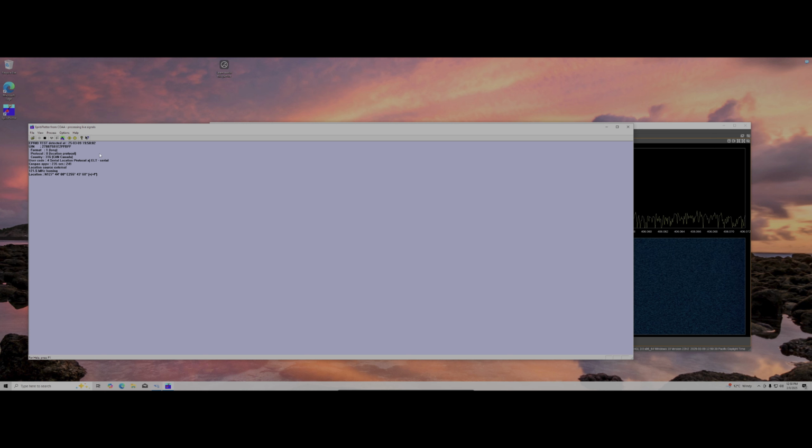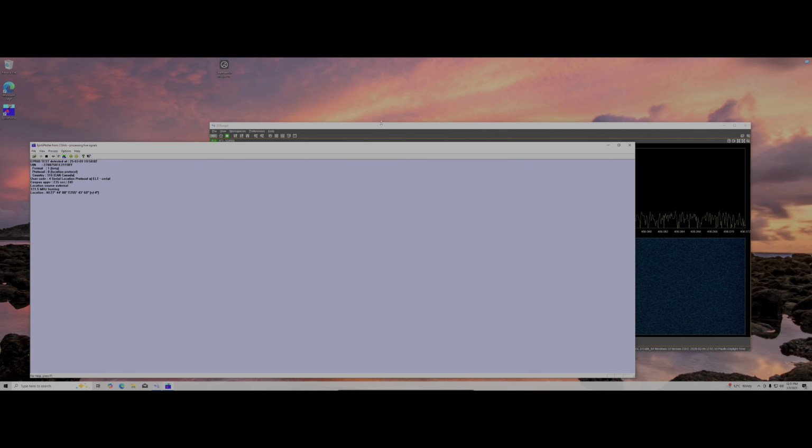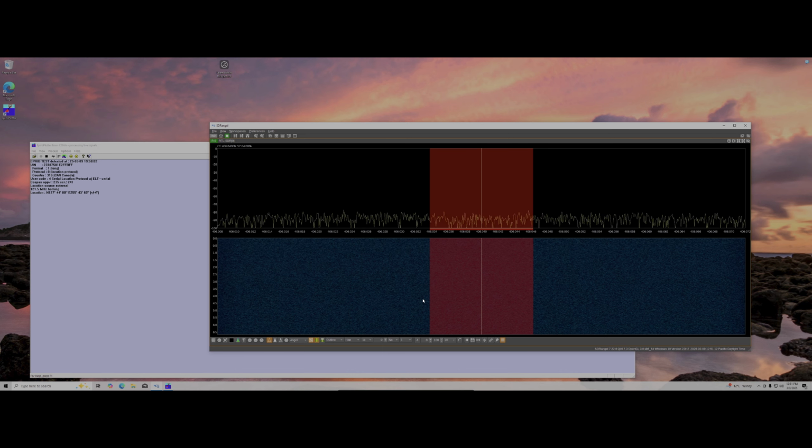It has the country code, the user code. It also has the COSPAS approval number, the serial number, as well as the GPS location. If you were to integrate your ELT with a GPS position, either like an ARINC from your aircraft GPS, or even like a standalone GPS specifically for the ELT itself, your ELT location will come up here as well. And that's really all there is to it. We should be able to just pick up as many ELTs as possible.